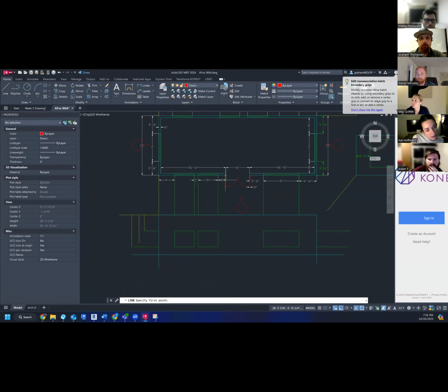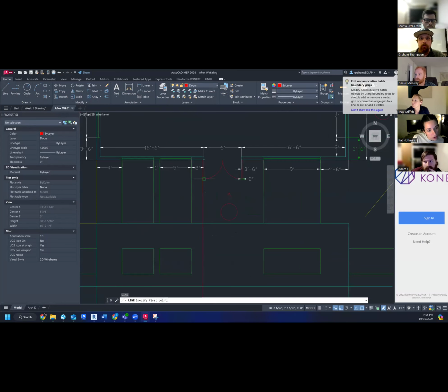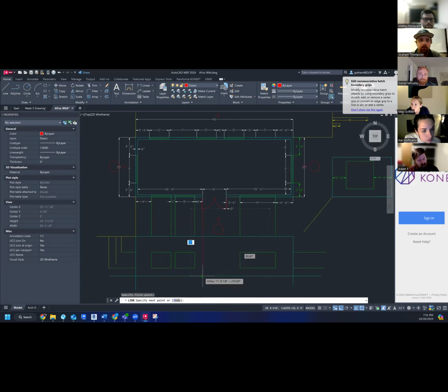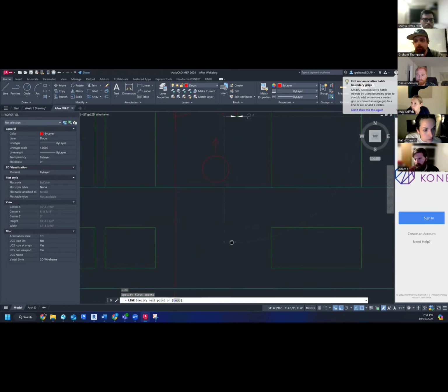And we're going to draw a line off the edge of our door. Same way, right? We're just transferring. And then for this one, let's actually just draw it off the inside edge, because we're not going to capture that thickness of the door when it's closed. Right? We're going to draw this door closed. So same thing here, off the inside edge. So this will represent a 6 foot opening, right?